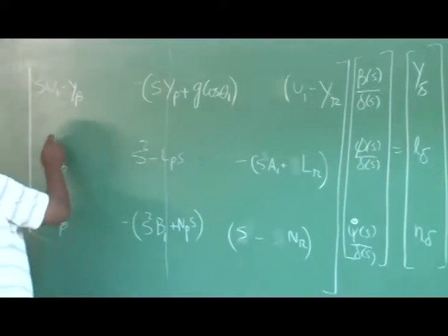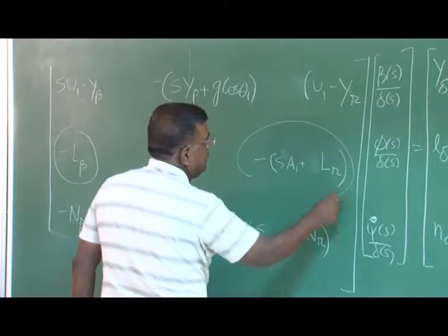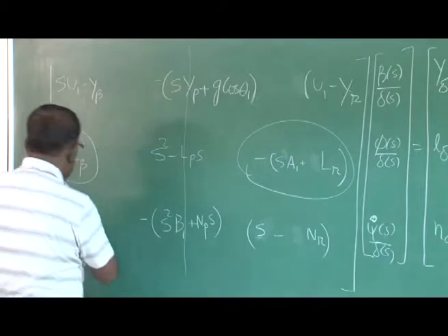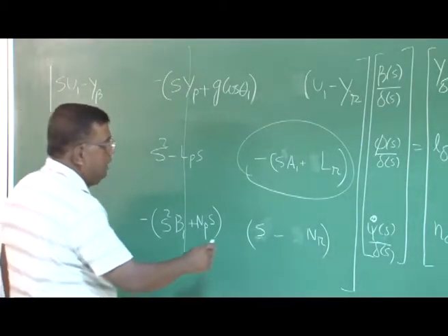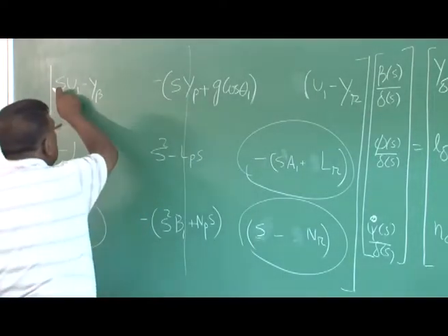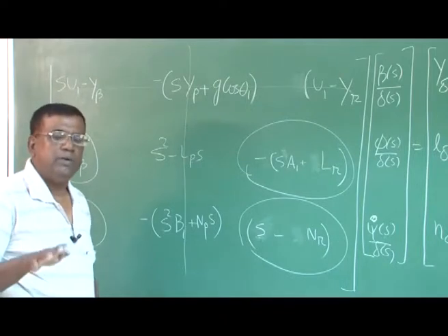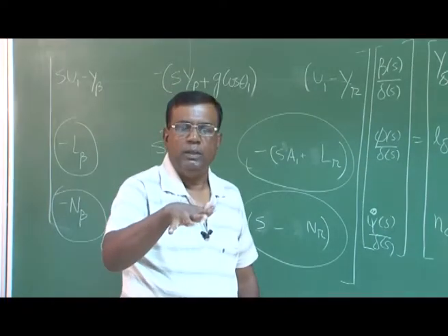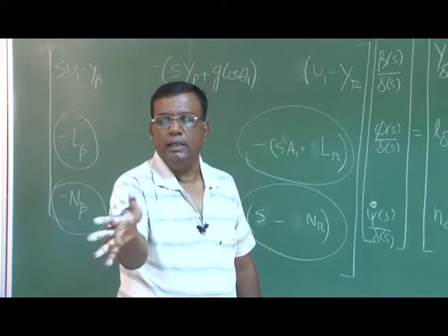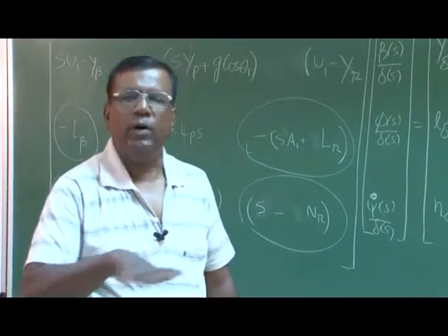What we are left with is this one, L beta into beta, this into psi dot, then N beta into beta, s minus Nr into psi dot. I am dropping this, I am dropping this, because in a spiral mode what I am focusing on is bank, sideslip, this, further bank, like this. So I am neglecting the effect of any force acting in the y direction.